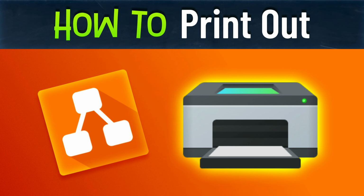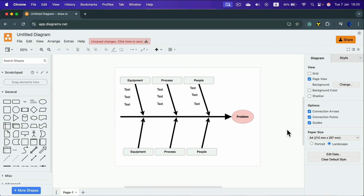How can we print out our Draw.io diagram? Before we head to print options, it's good to double check what is our paper size right now in the program. Just click in this empty area, not on any object, but in empty area. This way you can see the diagram properties on the right side here. And there will be a paper size. In my case, that's A4 landscape.